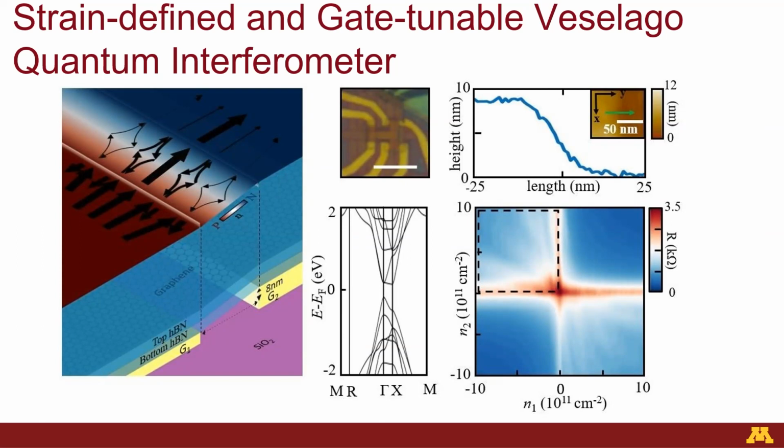Above the band structure, there is an optical image of the device. An atomic force microscope 1D scan was also performed. Here, the AFM data across the 50 nanometer gap region reveals that the device remains atomically flat on top of both gates as well as in the gap, while the lattice distortions are apparent at the boundary of both gates.